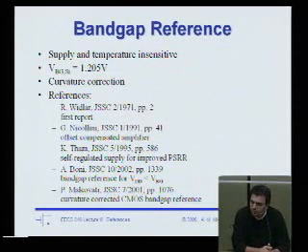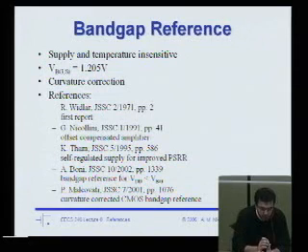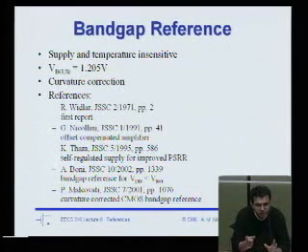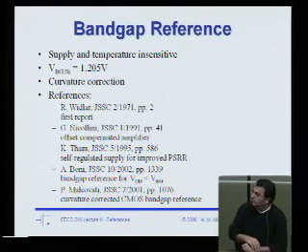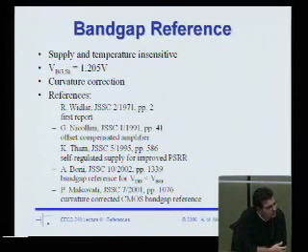If it's very important that you generate a precision current, then you probably have to, no, you definitely have to use an external resistor that is very precise, with a well-known temperature coefficient, very good precision, and then you can try to compensate, using that resistor, for the overall temperature dependence of your circuit. Okay. Question. Yes. Why don't you just make an on-chip resistor that has very large area?